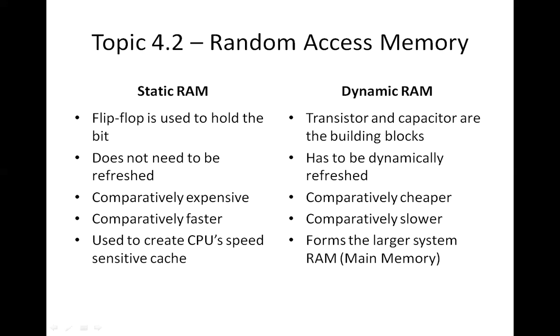Static RAM does not need to be refreshed. Once the data is stored in static RAM, it will be there as long as the power supply is there. But in dynamic RAM, the capacitor continuously loses the charge and hence it needs dynamic refreshment. So if we want the data to be stored in a dynamic RAM, there should be provision for dynamically refreshing all the charged capacitors.